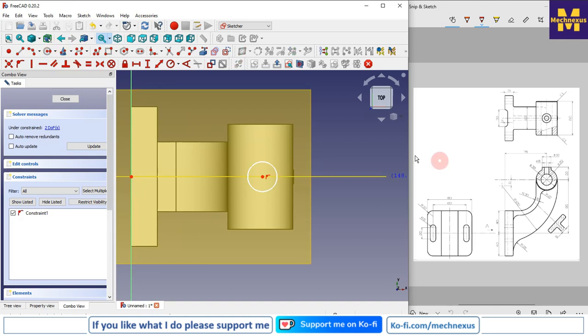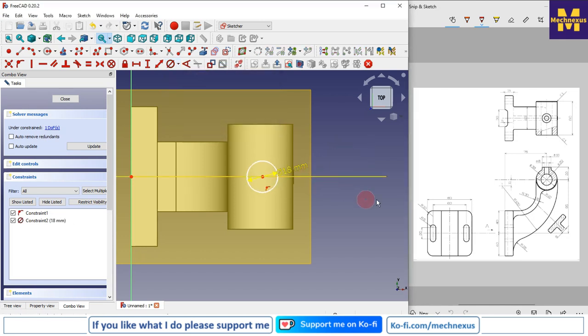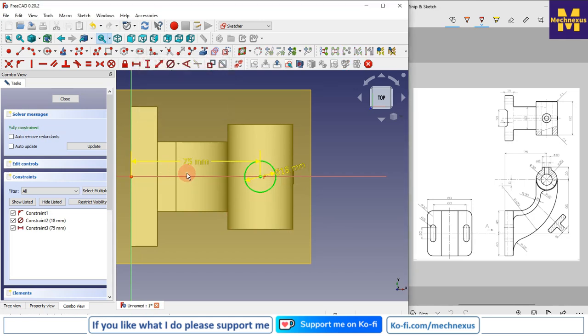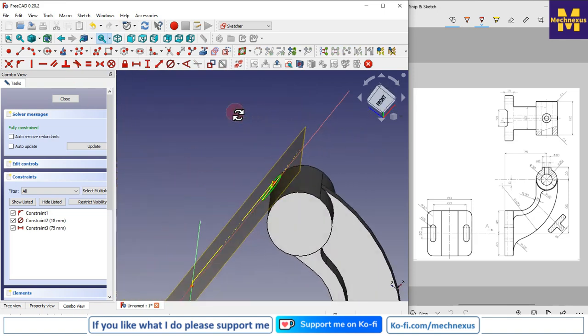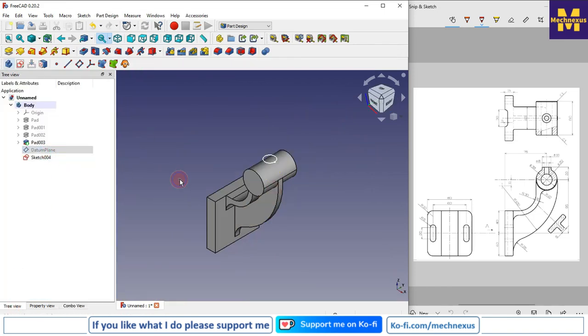My boss diameter is 18, so I will select this and give my diameter 18, and its position is 75 from the origin, so I will select this and give my dimension 75, and our sketch is fully constrained. I will close it and also hide my datum plane.